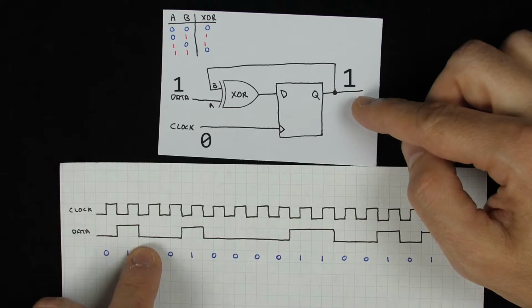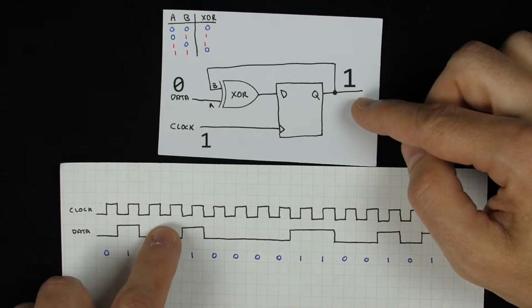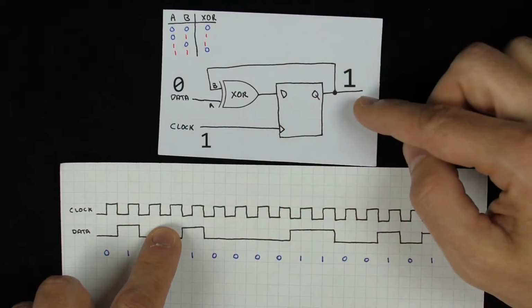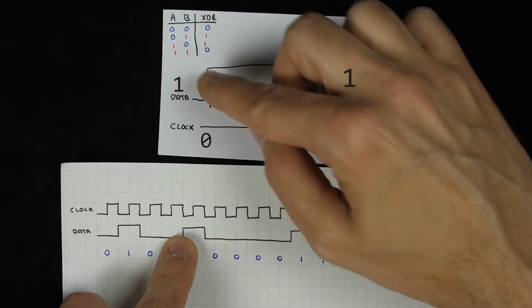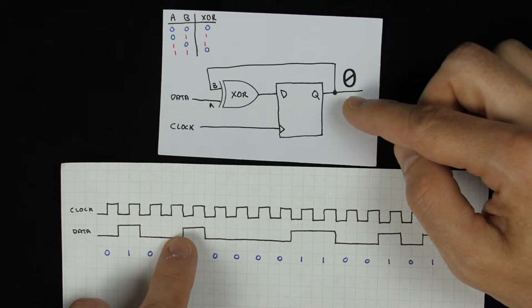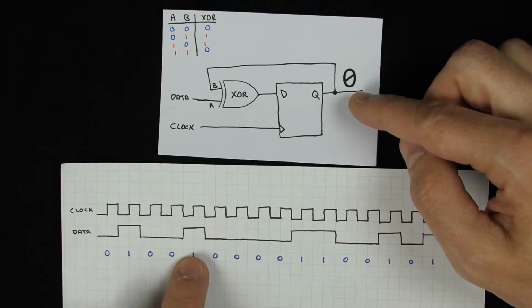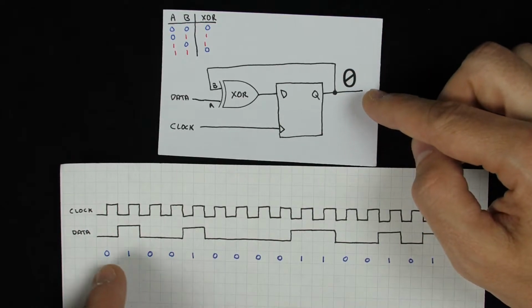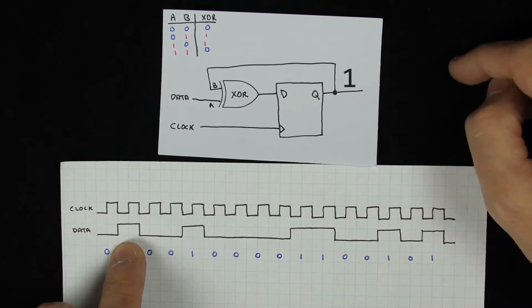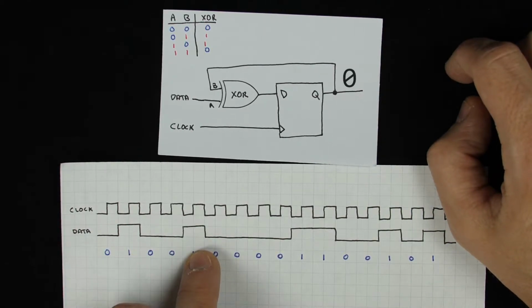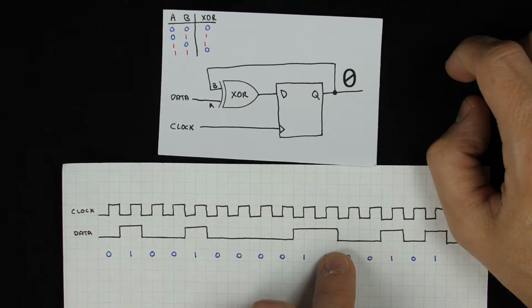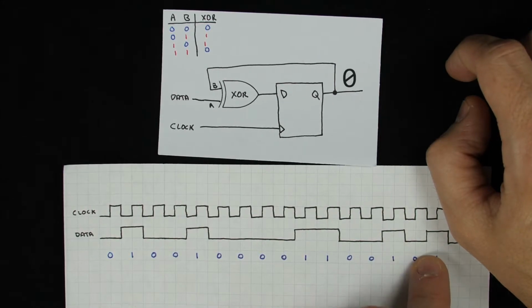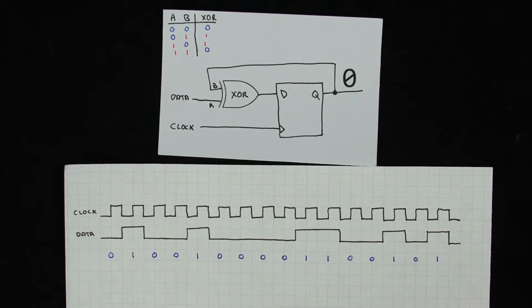And then when the data signal goes low again, then each of these clock pulses, we'll just feed that one back into the flip-flop and it'll stay high. But then when we send another one, we'll invert the input into the flip-flop again, and it'll go low. So in other words, every time we transmit a 1, the flip-flop will alternate states. Or in other words, if the flip-flop starts out off, then if we send an odd number of 1s, it'll end up on, and if we send an even number of 1s, it'll end up off. So if we feed our message into this circuit using our clock and data signals, it should compute the parity for us. So let's give it a try.